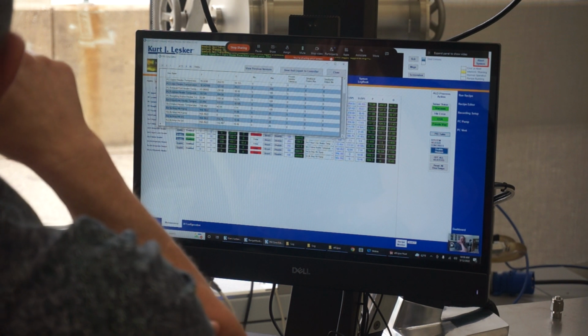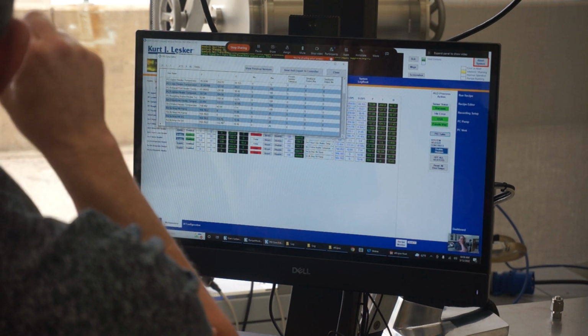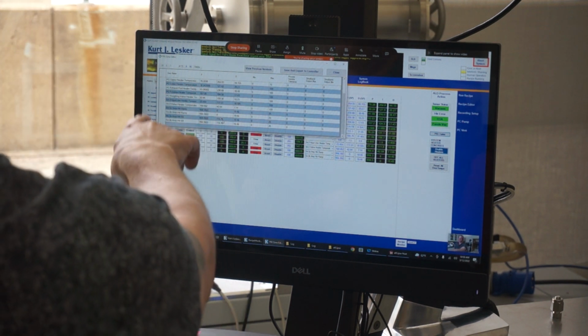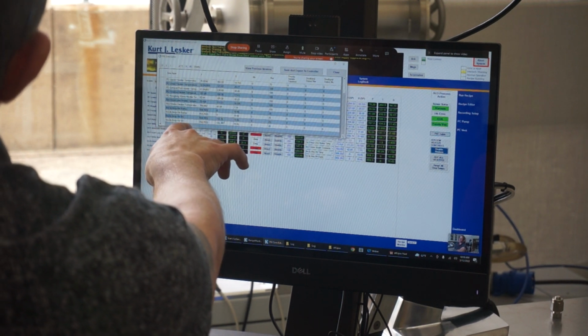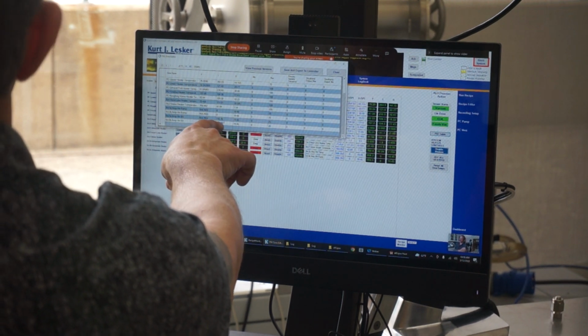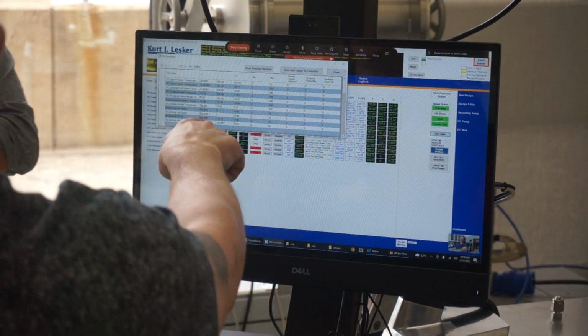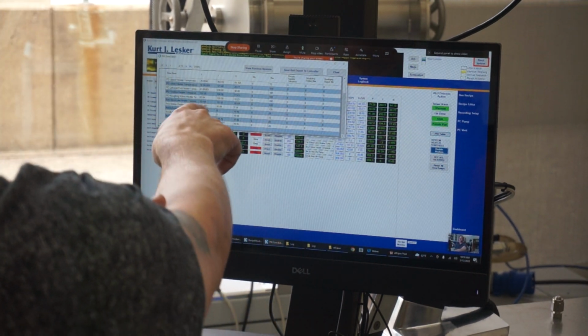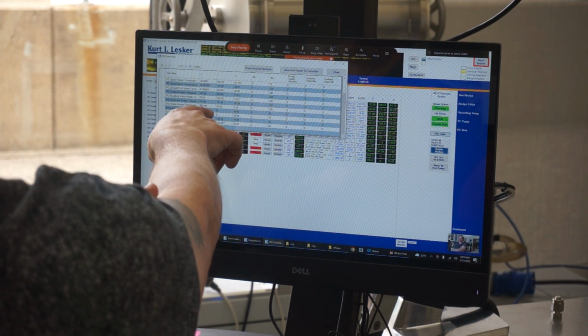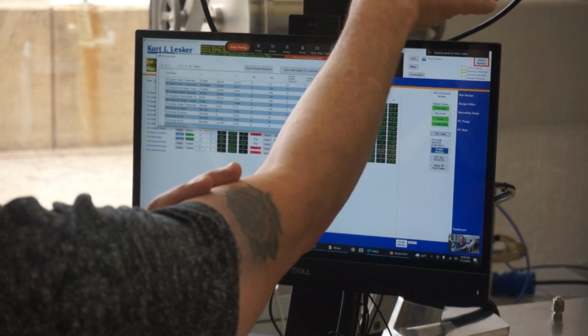Then the recipe will say whenever it hits 70 degrees, put in the different PID values in steady state, which incorporates I, and then it'll go from 70 to 75 with the incorporation of the I. What this does is prevent integral wind-up, so you don't have that overshoot.